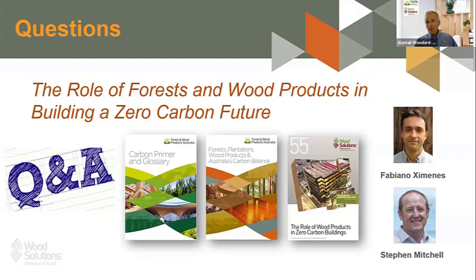Yeah, and as Steve mentioned, most EPDs cover the A1 to A3 stages. The transport part, which is often the impact with imported products, is under the A4 category, which some EPDs actually do give some advice around, not all, but that does need to be included when you're comparing a local or an imported product. Just reminding people of timber imports, if they've come out in containers on a ship from Europe, the amount of emissions occurring in the shipping of that timber is very low, because ships are reasonably efficient, and it's just one container amongst thousands on them. But it is important to include that A4 value as well.